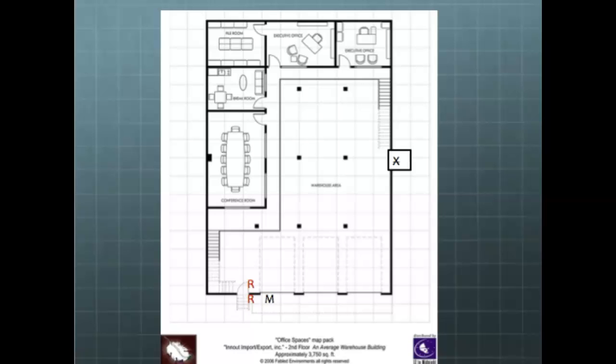I'll put a mag lock on that door. Electric strike will work just as well. I like a mag lock on it for a couple of reasons, mainly because, again, it's on the exterior of the building. I don't show an awning there. Normally a set of stairs going up to a door like that would have some kind of awning to keep the ice off, right? It also keeps the sun off in the summertime because they're metal doors and they tend to warp a little bit.